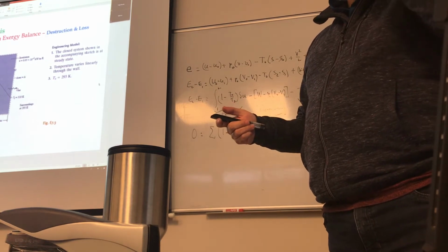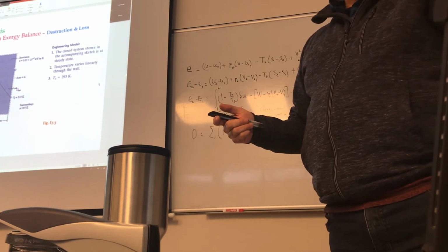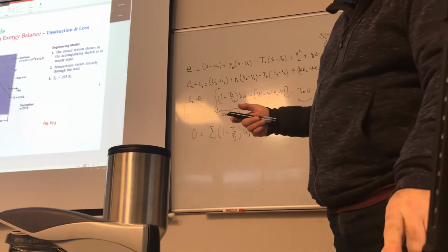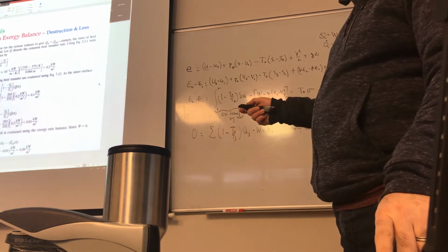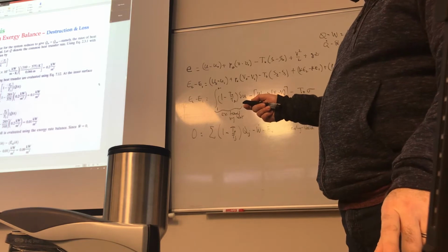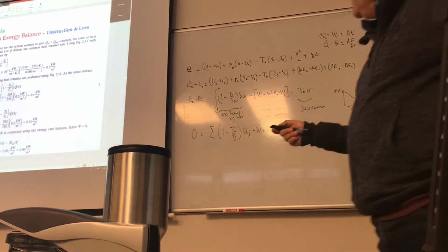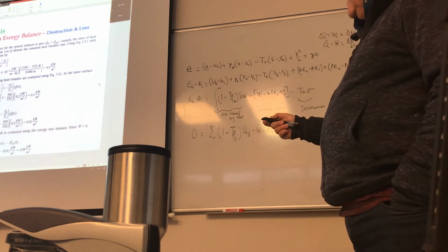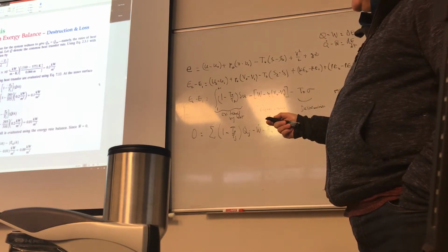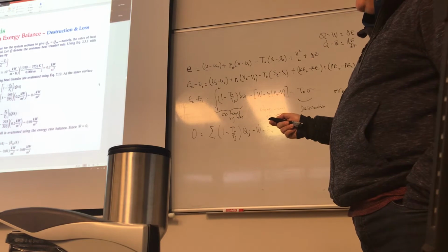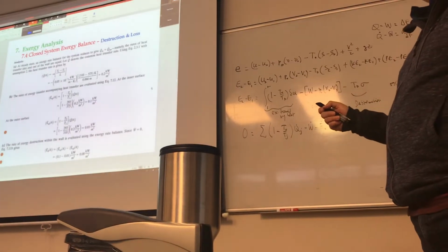It's 1, because it's told you per unit area. So we just use 1 for the unit area. So Q over A is minus k dT over dx. At the end of the day, it's 0.2 kilowatts per meter squared. That's the heat transfer that's going through the wall.